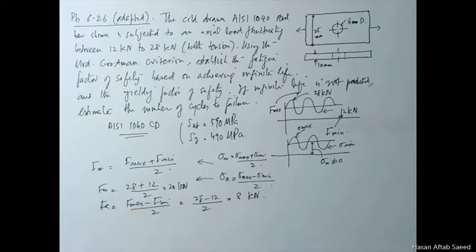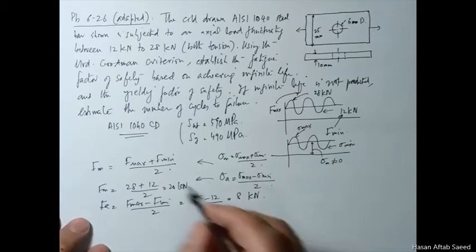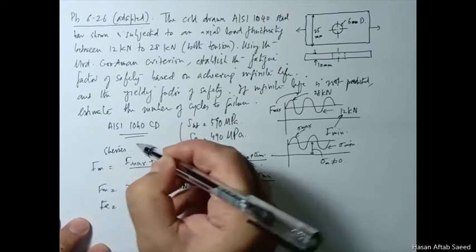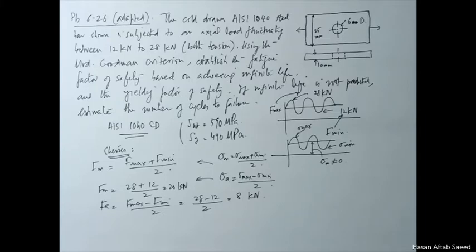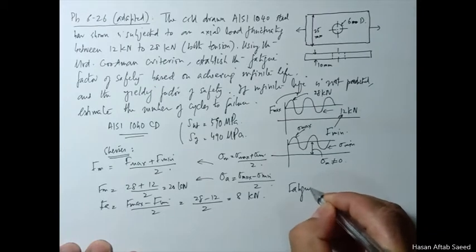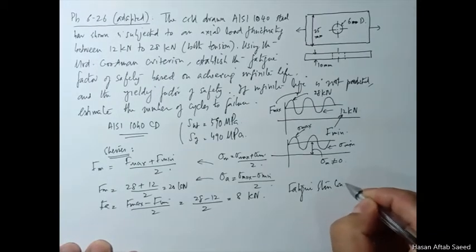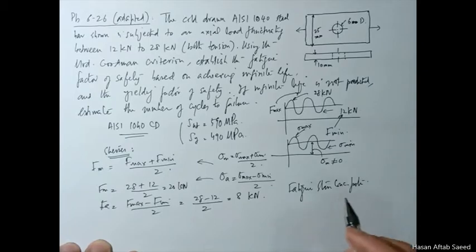Now for calculation of stresses, because we are dealing with stresses first, let's talk about stresses first. We'll talk about strength later on. Now the next thing is, we have just discussed that in this problem we need to have the fatigue factor of safety, with the fatigue stress concentration factor included. This is a fatigue problem. You just cannot take the stress concentration factor to be 1 anymore here. So Kf is needed. Now this Kf obviously is a function of two things.